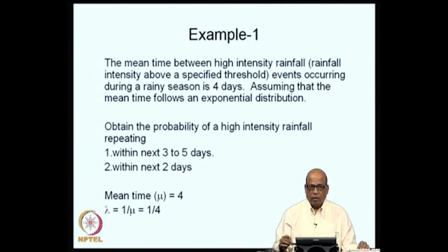In fact, those of you who have gone through an urban hydrology course will know that the time of concentration in urban hydrology situations will be quite small. For subcatchments, it may be as small as 12 minutes, 15 minutes and so on, and the design intensities we would be talking about would be of the order of 90 millimeters per hour.